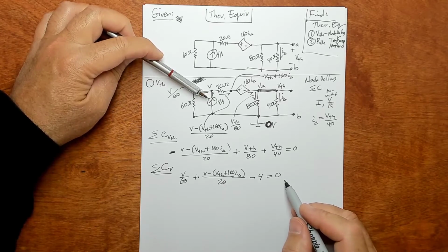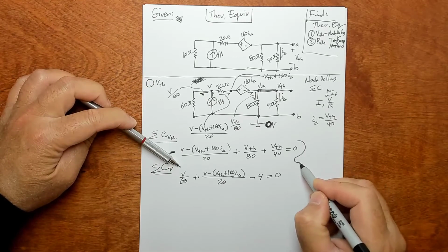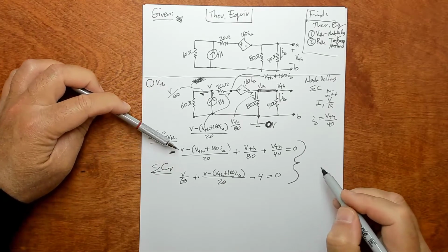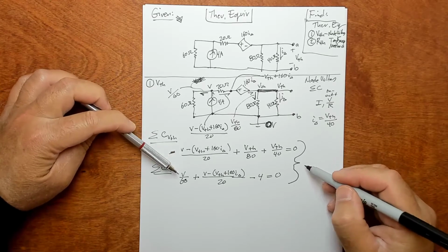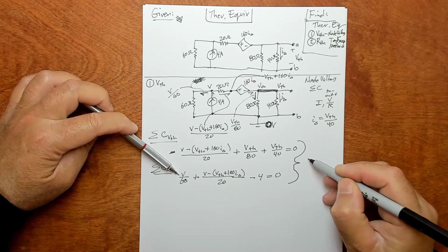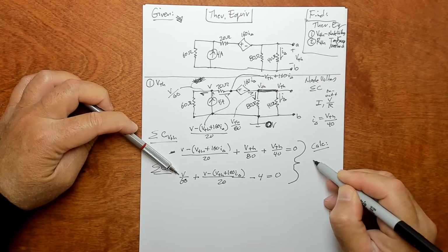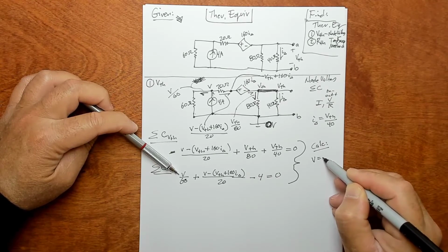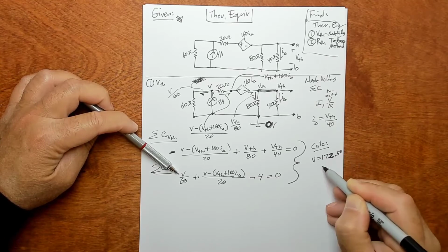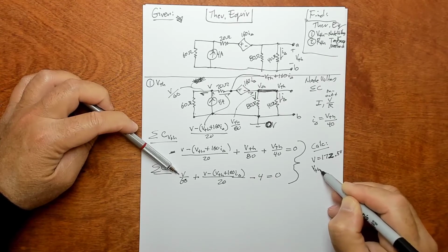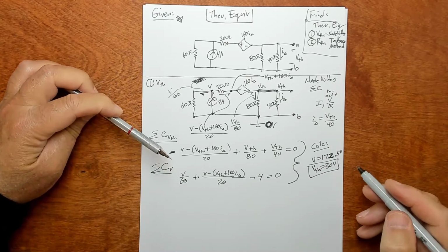So there's 2 equations and 2 unknowns in here, and I don't want to take the time to solve that because it's already a lot of work just presenting this stuff, but your calculator should be able to solve this, and what it's going to tell you is V is going to be 172.5 volts, and V Thevenin, which is what we want, is 30 volts. Okay, V Thevenin is 30 volts. That's the answer we want there.